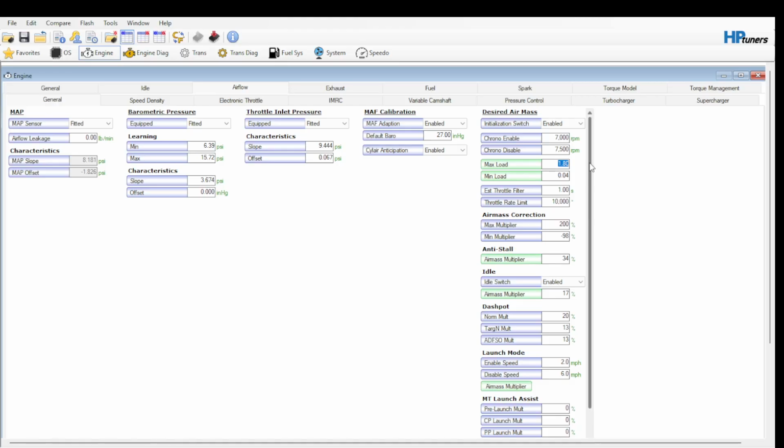The other thing that I've tested and seen failed over and over is just about every explanation for what the max load number means right there. I've heard people say that it's the manifold air pressure as a multiplier, like 1.8 or 180% of atmospheric. Wrong. It was at 198% atmospheric pressure at 1.74 load. So wrong. It's not that.